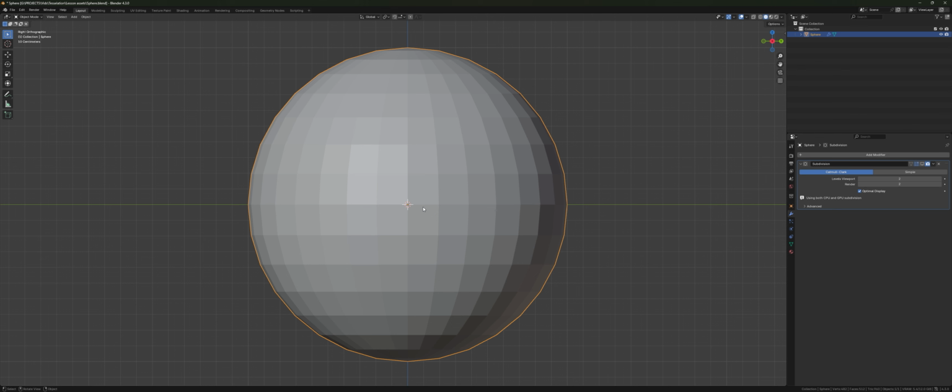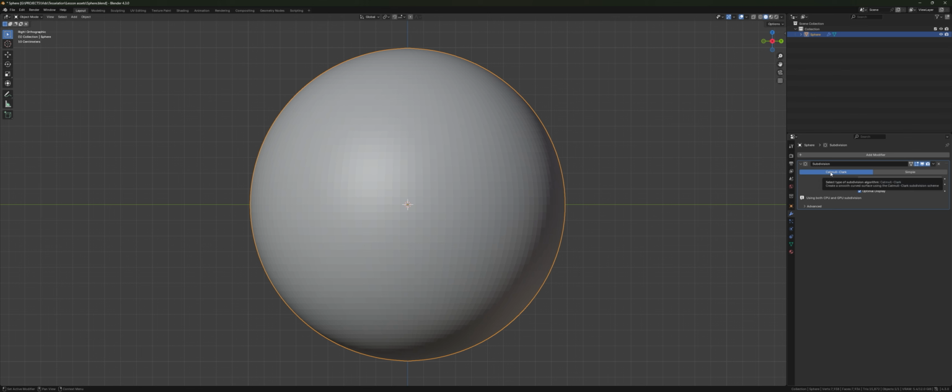So what I will do is apply it to my sphere. I'm going here, and I will apply a subdivision modifier with Catmull-Clark activated. Here we go. So as you can see, this algorithm ramped up the complexity by subdividing a mesh without overlaps into smaller chunks and smoothed out the model. That is what the subdivision modifier under the Catmull-Clark tessellation algorithm does.